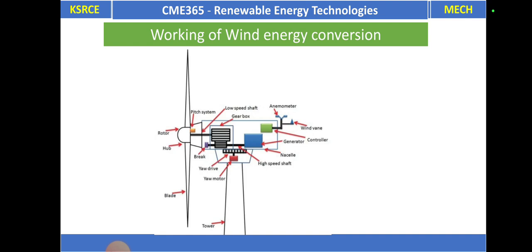A tower produces turbulence behind it. The turbine is usually pointed upwind of the tower. Turbine blades are made stiff to prevent them from being pushed into the tower by high winds. The blades are placed at a considerable distance in front of the tower, and they are sometimes tilted up a small amount. Downwind machines have been built despite the problem of turbulence because they do not need an additional mechanism for keeping in line with the wind.